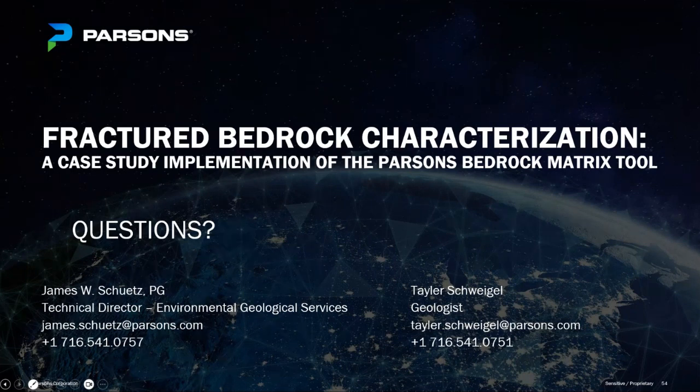Depending on the level of impacts, for example, if you're in a DNAPL source area, which I try not to even drill through, but if you're outside of it, and depending on your risk to receptors, you can leave a borehole open for short periods, and that's what we did at the case study. We knew that the contamination was to a certain depth anyways, and even though we do have HSUs, there must be some communication through, which allowed the plume to go deeper.